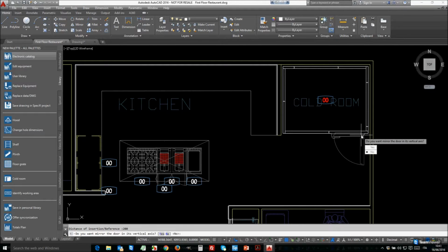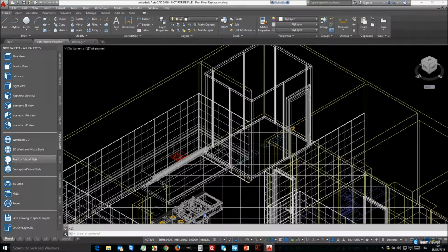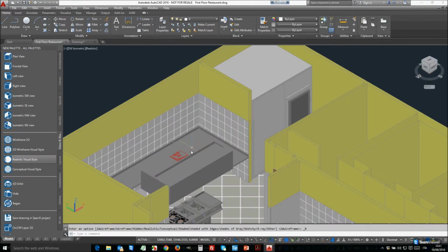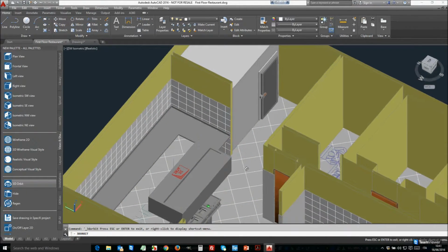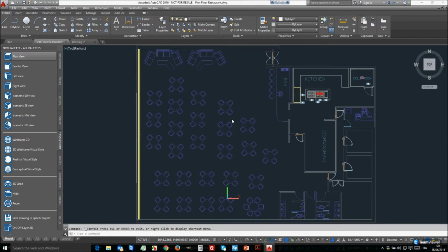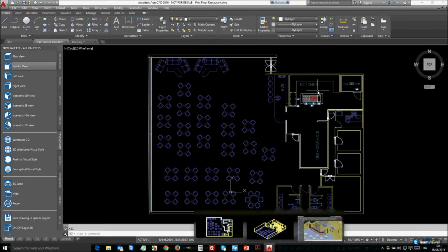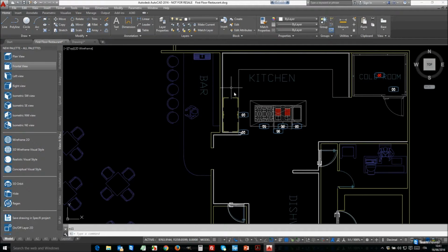And now I just have to, from a catalog, we have always in our special library a command to insert, for example, the door accessory for the cold room. I have a door that I can insert, selecting inside the panel, outside, and the distance 200 millimeters from the corner. I can mirror also the door. In this case, I choose no. And you can see the result in 3D. In 3D, you have your cold room just created.